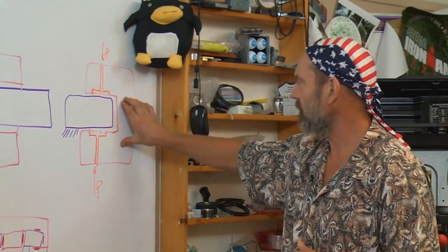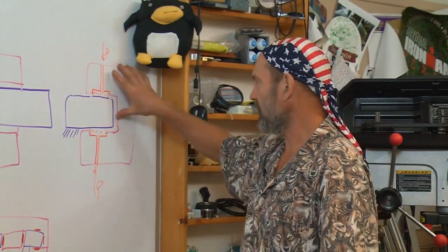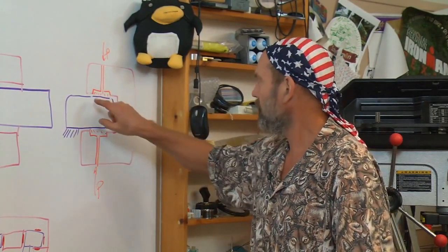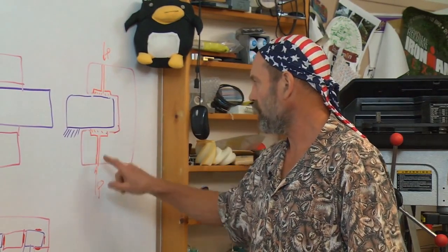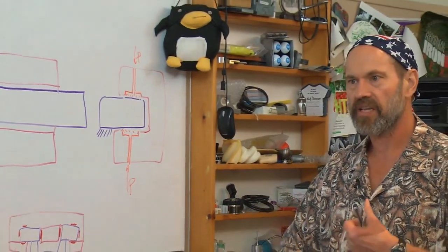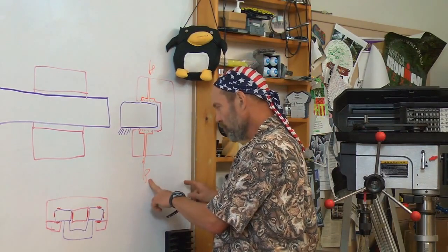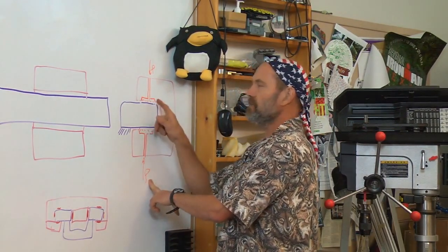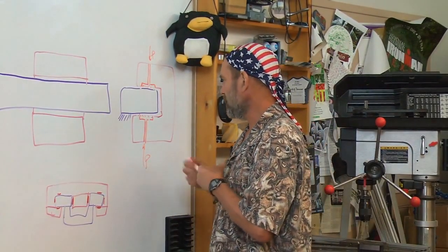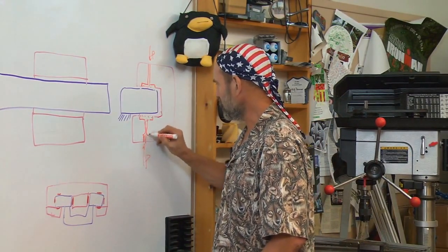And you say, yeah, but if you push down, this will form a seal in here, and it's got to pick it up. But if it's the same pressure either side, you say, well, it's not going to be the same pressure, because if you push this down, there's no gap here, there's a big gap here, and it's going to have to leak and have a lower pressure. And now, by that reasoning, you're starting to realize, aha, I actually don't want to have pure pressure from the pump applied to both of these pockets. I want to have the pressure that goes into each pocket actually go in through a resistance.